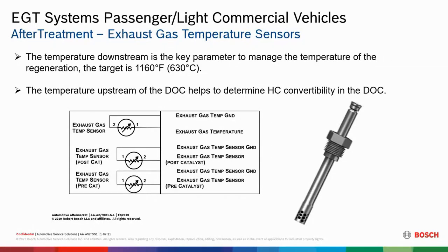So these are a lot of problems getting them out of the system. Even after a short amount of time, they're in a corrosive atmosphere. And I don't mean just the DEF fluid's corrosive, but the exhaust fluid itself is corrosive as well. The exhaust is just the exhaust itself and the high temperatures cause these things. They're very small and they break off quite often. So it's a challenge to mess around with these, especially once it hits a 50,000 mile mark, they can be a challenge to get in and out of there.